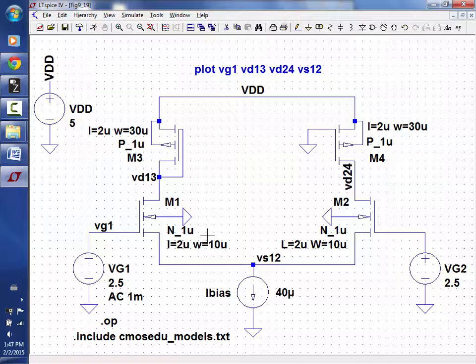So when we're trying to get good matching, which means have two currents and two devices behave electrically the same, one of the key things we're going to focus on is trying to equalize the drain to source voltages. So nowadays when you do designs, say at Qualcomm, using a 15 nanometer process, the matching, because those devices are so tiny, you can literally count the number of electrons underneath the gate, or in the channel, or the number of atoms used to manufacture the device.